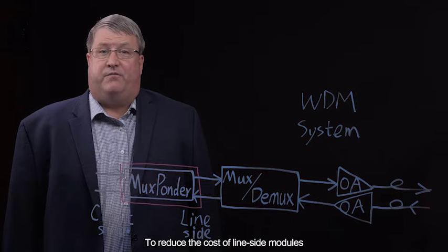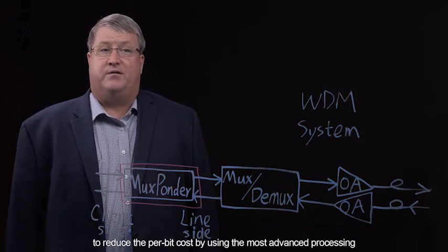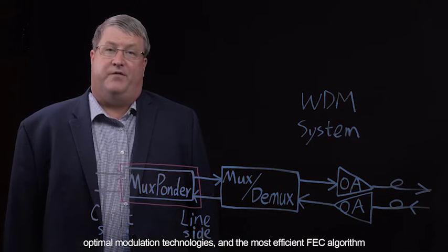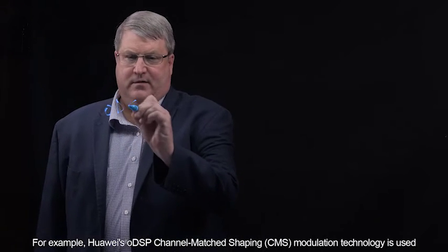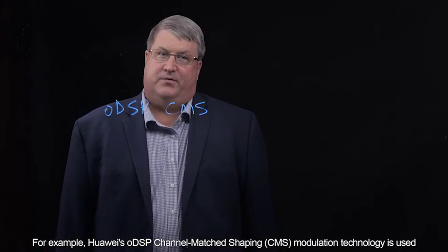To reduce the cost of line-side modules, the single wavelength rate and performance need to be improved to reduce the per-bit cost by using the most advanced processing, optimal modulation technologies, and the most efficient FEC algorithm. For example, Huawei's ODSP channel-matched shaping modulation technology is used.